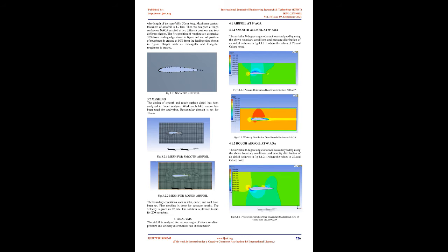Impact of roughness factor on aerofoil. Roughness. Surface roughness, often shortened to roughness, is a component of surface texture. It is quantified by the deviations in the direction of the normal vector of a real surface from its ideal form. If these deviations are large, the surface is rough; if they are small, the surface is smooth. In surface metrology, roughness is typically considered to be the high-frequency, short-wavelength component of a measured surface. However, in practice it is often necessary to know both the amplitude and frequency to ensure that a surface is fit for a purpose.